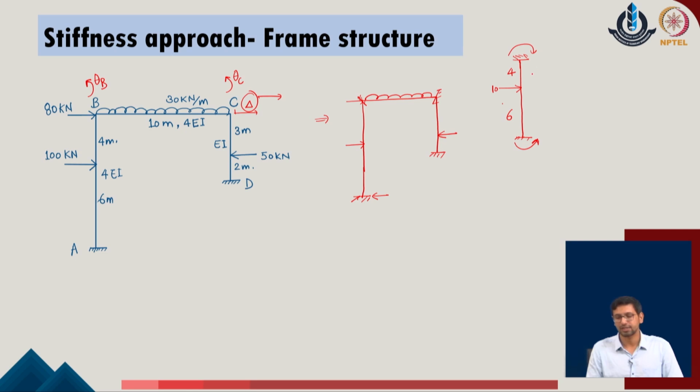We realize that these end moments, typically if I define this value as A for the given system and this value as B for the given problem, and this load parameter being P, we can understand that the given moment values come out as P A square B upon L square at this end, and over here it comes out as P A B square upon L square for the given system.